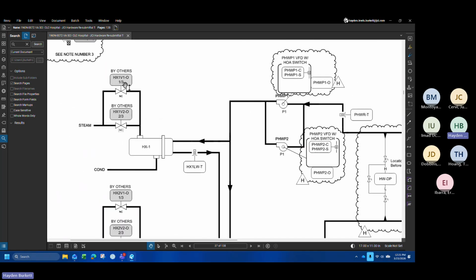You can see we wrote essentially one of these actuators is only 1/3 of the control, and the other is 2/3 of the control. So if it's only operating at like a low load, you would expect to see basically only the first stage of this opening to maintain.